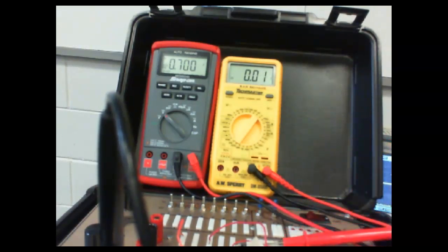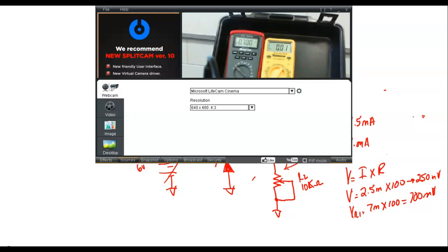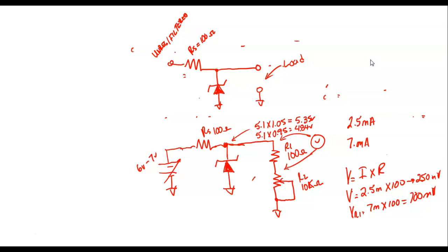So what we did is carry our power supply across the range that we designed it to handle. Now we need to figure out the percent regulation. What is the Zener rated at? It's rated at 5.1 volts. What was the maximum voltage we got out? Maximum, I think, 5.04. And what's the minimum we got out of our Zener?